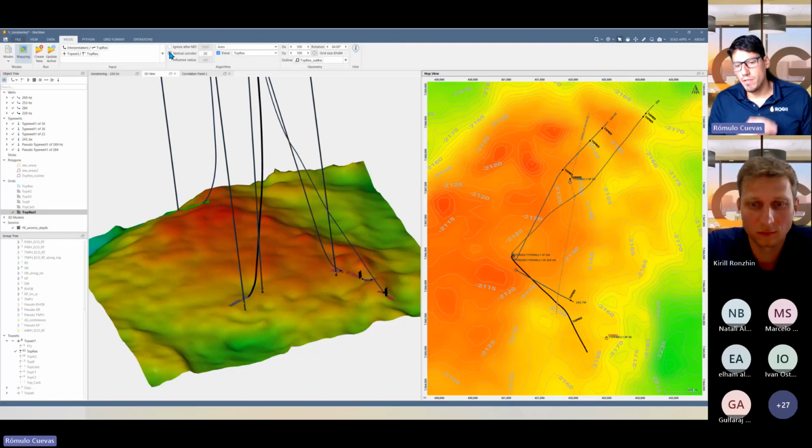So sometimes you have information when you cross the layer with your trajectory, but in some points this layer is already far away from the borehole. So you are just estimating that horizon. So when it's really far away, you can just apply a constraint and remove those data points that are really far from your borehole in here. And also you can apply influence radius, so you can affect just the area you want to affect around your grids, and you can always update the new grids here.